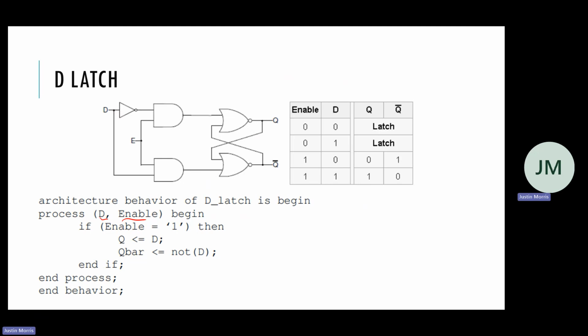So that's what I meant every time I was talking about these process blocks, that it would create a latch if you did not define your default case. So there's no default case here, there's no else. So that's why it's going to just hold on to the previous value. And that's how it's going to get this latch behavior.